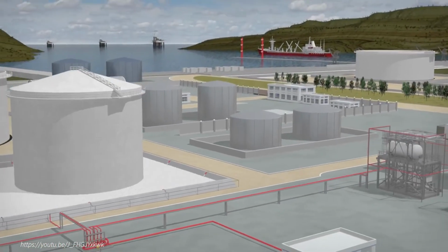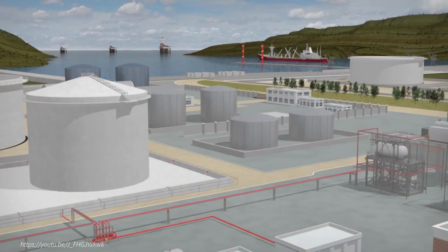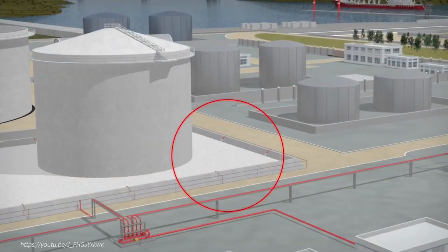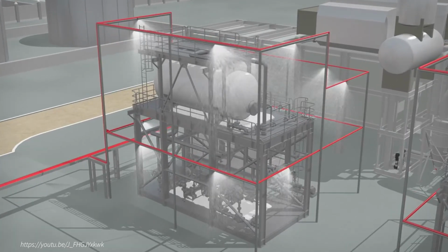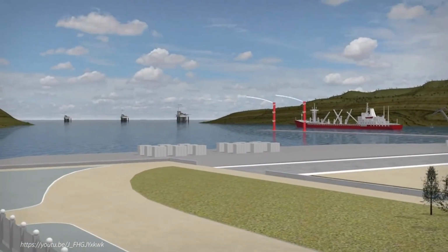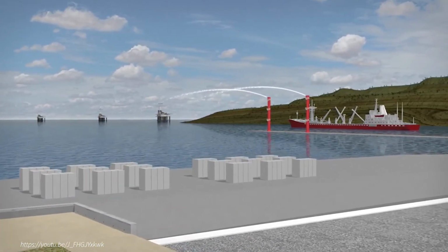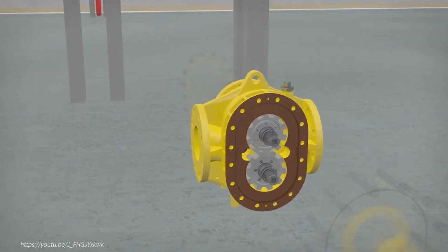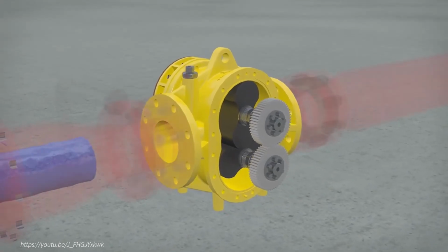The Turbinator can be incorporated into any existing type of foam firefighting system onshore or offshore, whether in storage tank farms, for bund areas, tank protection with foam pourers, deluge protection of process plant, or in jetty foam systems including Knowsley tower-mounted remote-controlled monitor systems. The Turbinator comprises 2 main items closely coupled into a single unit. These are a water motor and a foam pump.